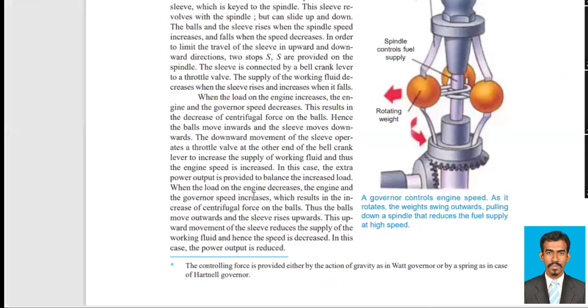When the load decreases, the engine speed increases, which results in an increase in the centrifugal force of the balls. Thus, the balls move outward. We know that if the centrifugal force increases, the balls will move outwards, and the sleeve will rise up.